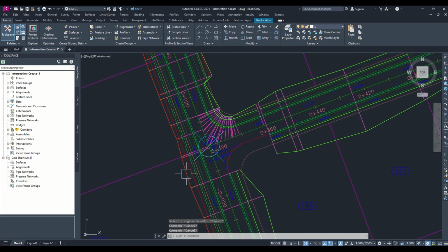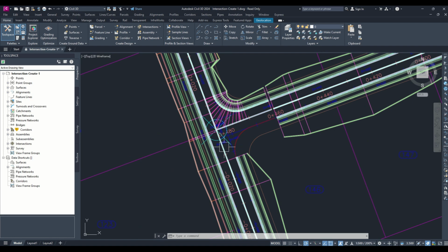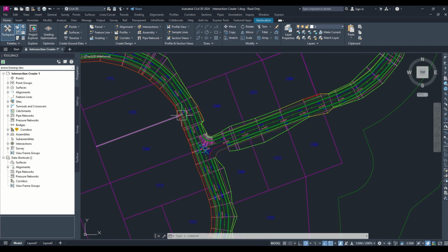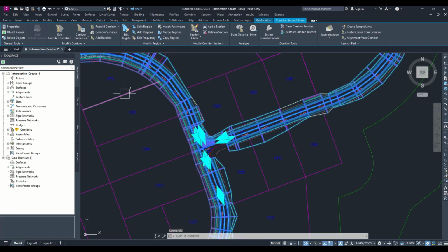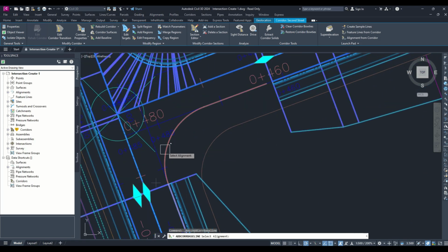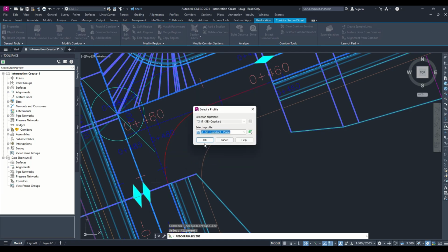Now we're just going to repeat what we have done in the past, so that we make another curb return here. So how do we go about that one? Okay, we select the corridor, which is another word for road. Anyway, for 3D, just call it a corridor. Okay, so I'm going to add, like I did, the baseline here. I've selected the baseline. I'm going to select the line, which is this one. Okay, once I'm done with that, I'll click OK twice, like I said first.